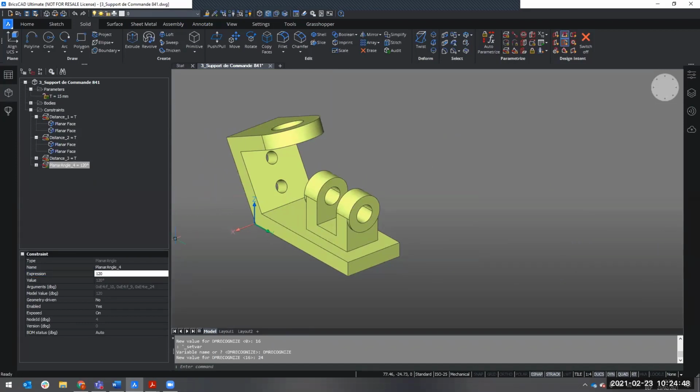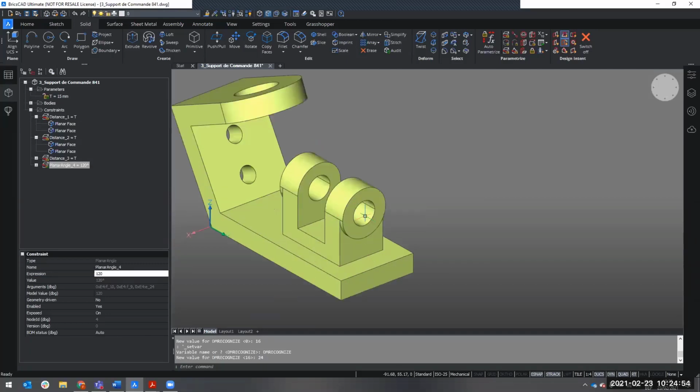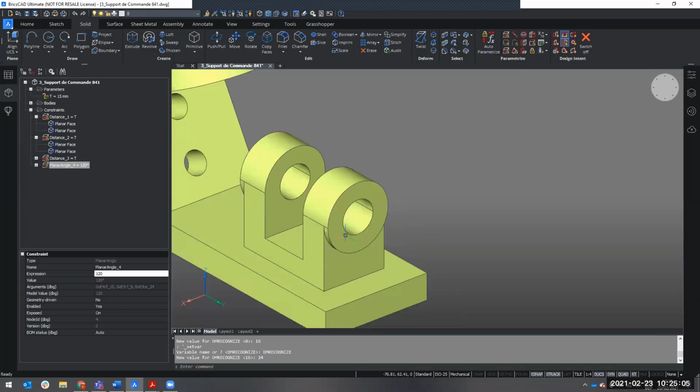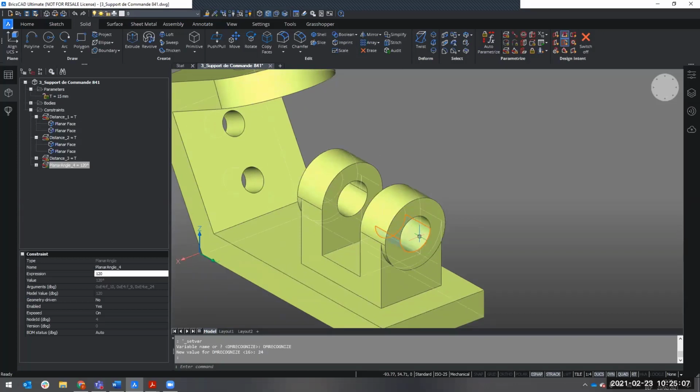Then we're almost finished, I think, with this exercise, and we are still wanting to apply an equal radius, because we actually don't have a radius constraint yet. So we first want to set a radius constraint so that we can control this radius. So you want to set a radius constraint by putting here the radius option.